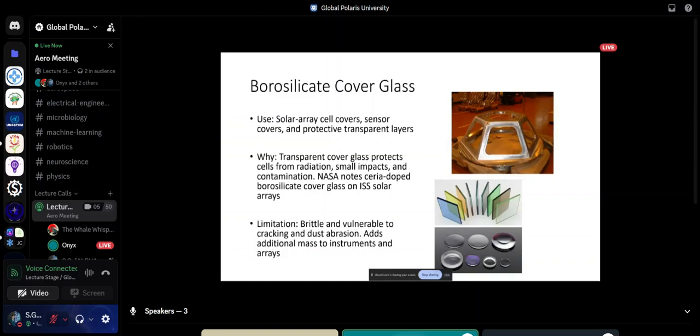Typically, whenever we measure instruments, we just measure them as is. We don't measure them with a coating of paint, which I mentioned paint specifically because paint gets very, very heavy when you apply that to a rocket or missile. Often we try to coat rocket bodies white as opposed to a darker color, just also because of thermal issues as well.